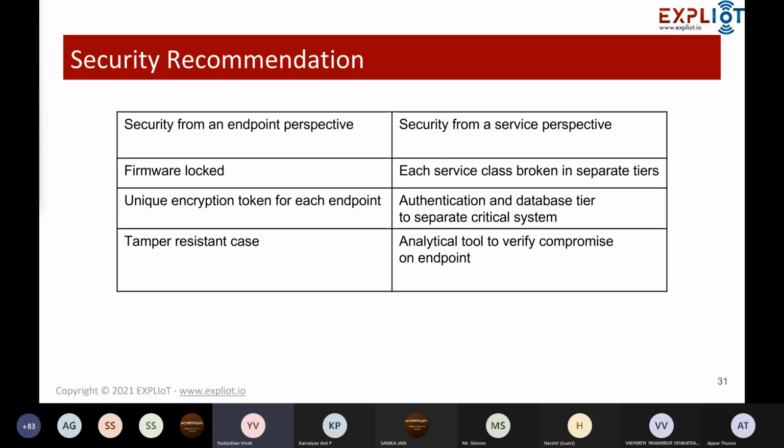Possibly we can have an OTP memory where you flash it once, as well as different levels of security from the ports and debug perspective, so that the read and write functions for external users are not there. Also, when you are sending data from the sensors with device IDs, for example, if it is tracking people in the complete manufacturing plant, it is expected that everyone sending the data should be encrypted, right? And those encrypted things should be sent to the server.